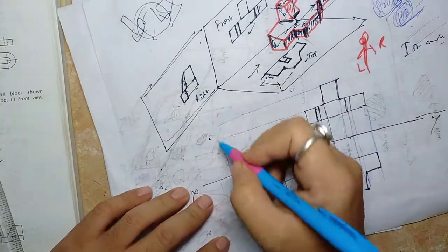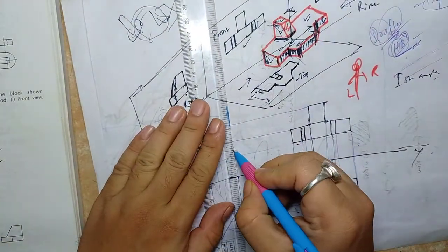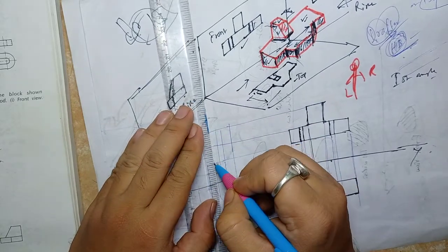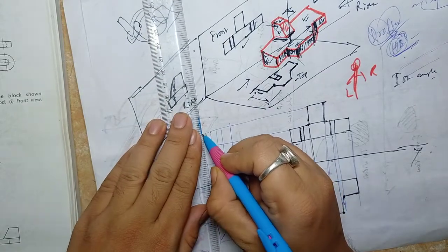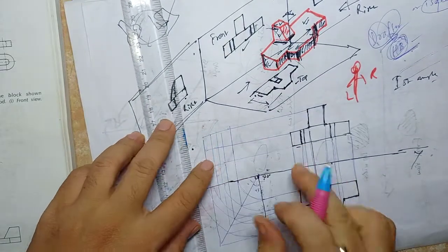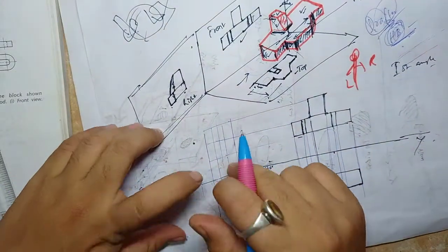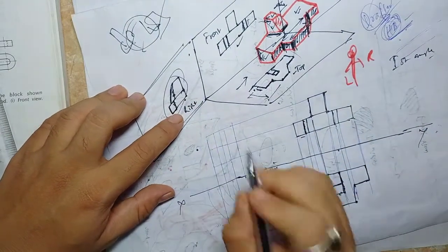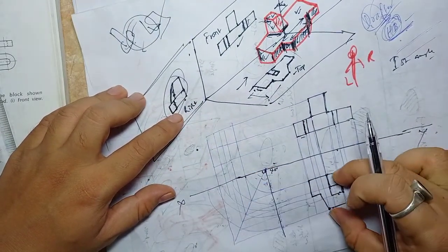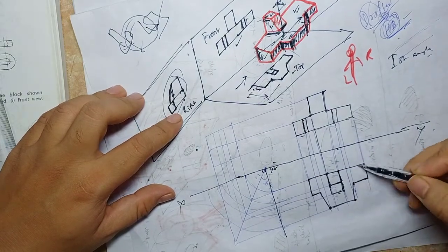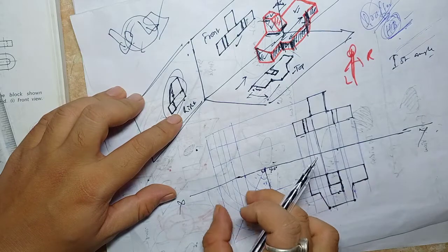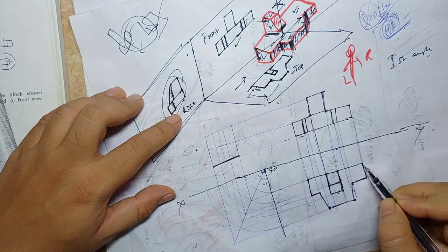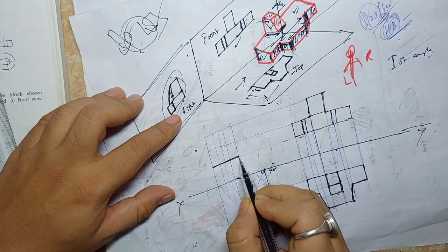Okay, now once they go up, what you have to do is draw these lines so that they match, or intersect with, the lines coming from your front view. Okay, here now you roughly know how your right side view will look. Now you see these lines are actually carrying information from this edge, this edge, this edge. So they are here exactly equal, and this edge is also there. So we can draw an edge here. Okay, this side and this side together. Okay, we have drawn it here.